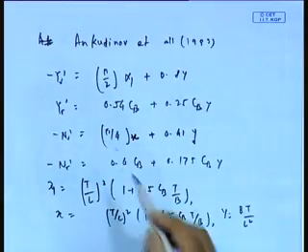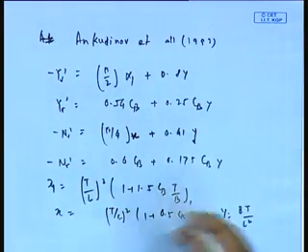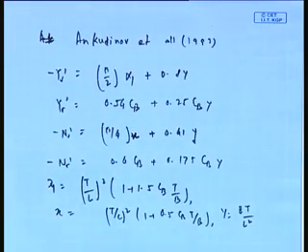What I am saying is that I wrote very quickly. You can always look back at that from any book, but the main point I want to tell here in these formulas is that there is no uniform formula. Theory tells us, based on many approximations, that these quantities are in proportion to T by L. Reality of course shows that it will not be only T by L, because then there is no sensitivity to geometric parameters. So then people started collecting data, making a formula based on regression. When you talk about theoretical determination of maneuvering, it is mostly based on regression type data.